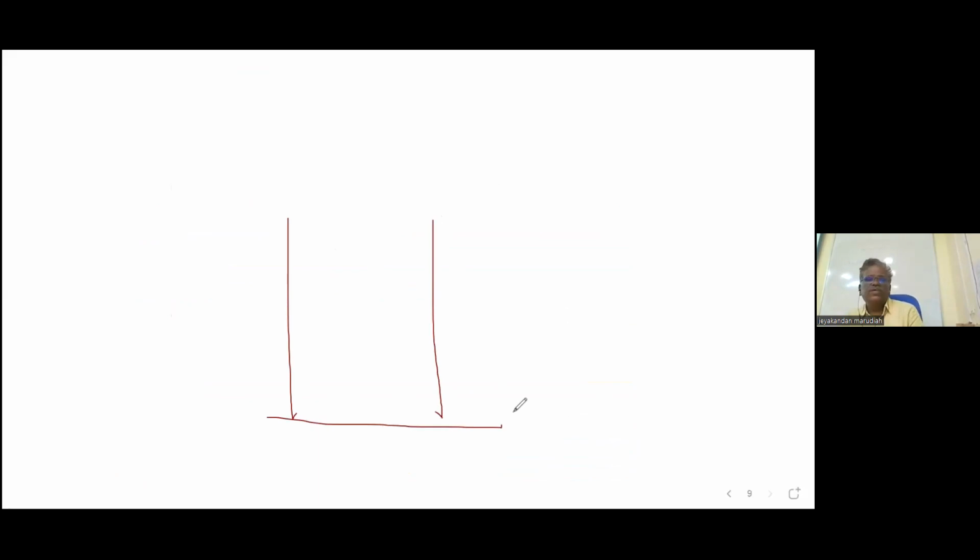Which is filled with oil. So this is my roof, and I want to install a nozzle here. So how to install a nozzle? First, we have to prefabricate it. Prefabricate means we have to take a plate here and weld a nozzle here.